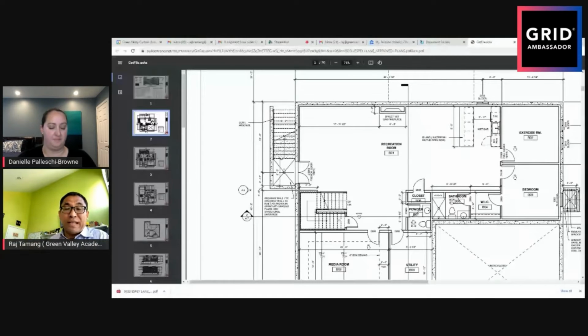That's all the grading plan. The grading plan will also tell you the elevations. What is the basement elevation? What is the first floor elevation? What is the roof? All that information will be on the grading plan. If you look at the building plan, you really don't see the elevations, the height or depth of the basement level from the ground outside. You don't see it. You have to go to the grading plan.